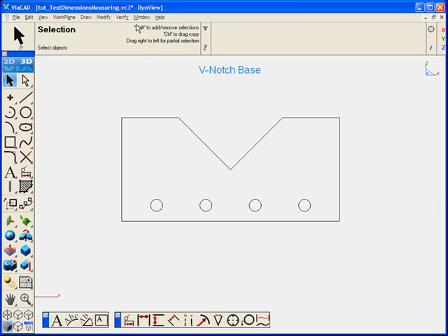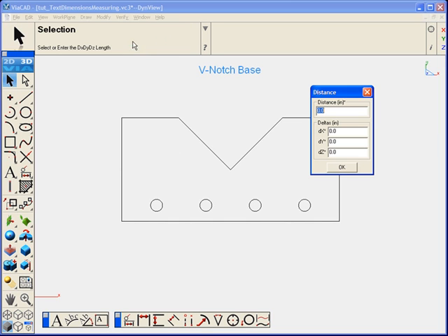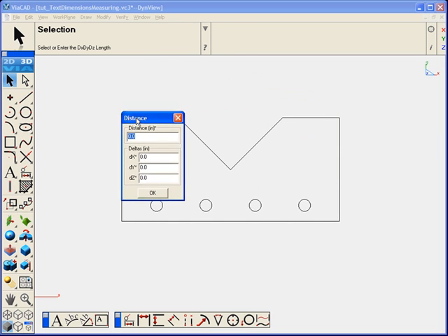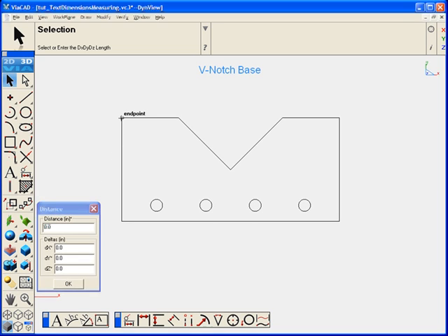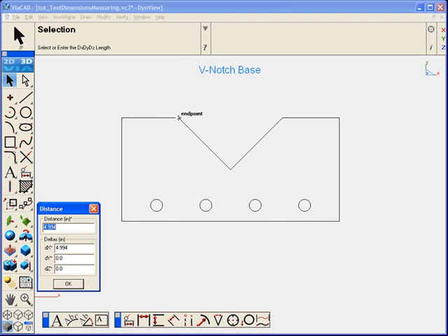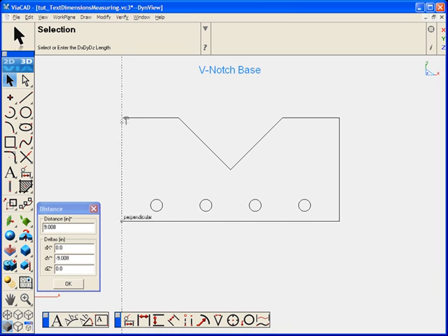And now to measure the drawing, we'll go to the Verify menu. This allows you to actually do measurements without doing dimensions. The Distance Point-to-Point tool allows you to pick 2 points anywhere in the drawing, and it measures the distance between them and then gives a delta between the 2 points. The delta is the relative distance between the x-coordinate, y-coordinate, or z-coordinates between the 2 points picked.